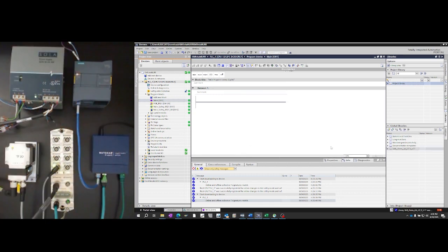Once the library has been successfully upgraded from its original version 14, which you downloaded from the website, it'll now be available in version 17. And you can see that here under Global Libraries, SMS Festo Library version 2.3, version 17. Expanding that library, I'll be able to add 4 function blocks to my main program. Today I'm going to be using the advanced function block for specific features down the road.